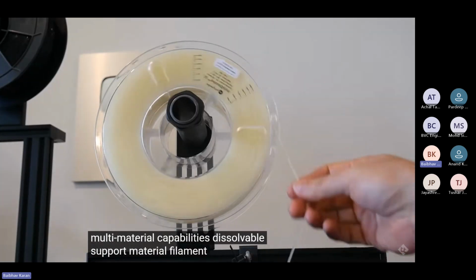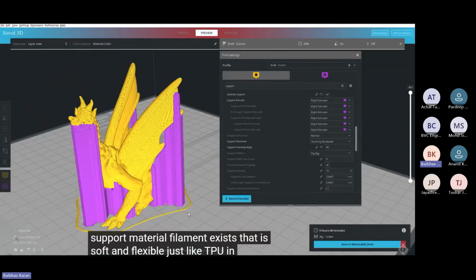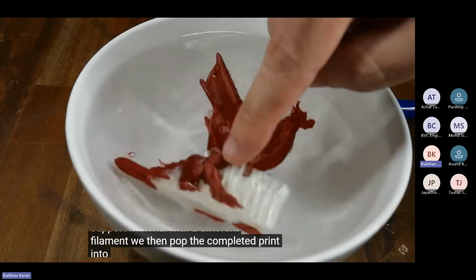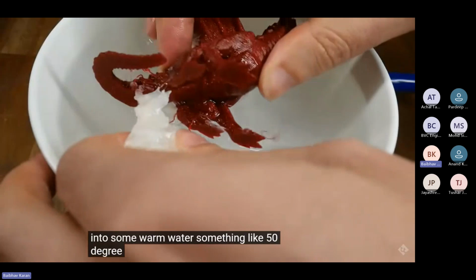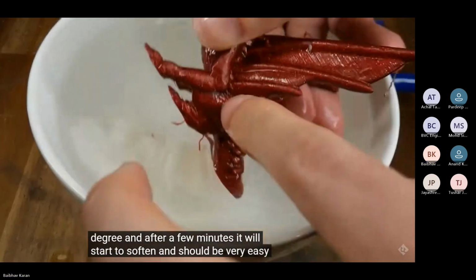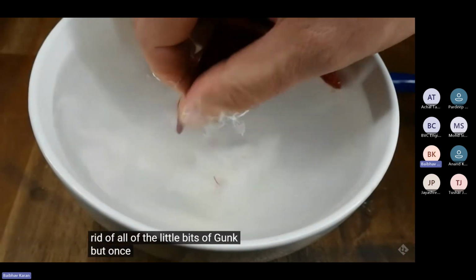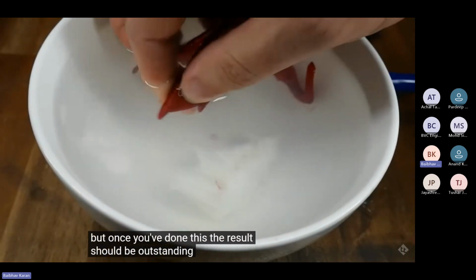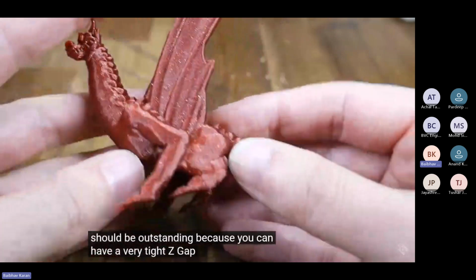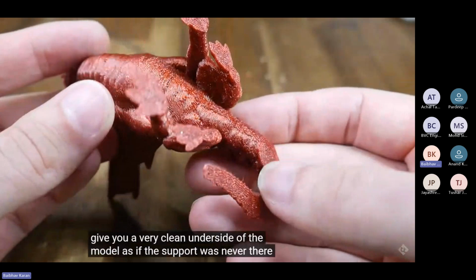Dissolvable support material filament exists that is soft and flexible just like TPU. In these cases, we tell the slicer to print the support material with a different filament. We then pop the completed print into some warm water, something like 50 degrees, and after a few minutes it will start to soften and should be very easy to remove. You'll need to wash it to get rid of all of the little bits of gunk, but once you've done this, the result should be outstanding because you can have a very tight Z gap, and that will give you a very clean underside of the model as if the support was never there.